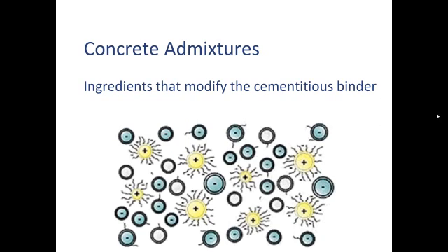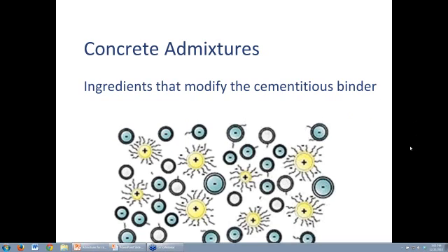And I have the latest edition of the Portland Cement Association's Design and Control of Concrete Mixtures, and their Chapter 7 on chemical admixtures for concrete lists the 4 major reasons for using chemical admixtures in concrete. And I will quote, "To achieve certain properties in concrete more effectively and efficiently than by other means. To maintain the quality of concrete during the stages of mixing, transporting, placing, finishing, and curing, especially in adverse weather conditions or intricate placements. To overcome certain emergencies during concreting operations. And finally, economy."